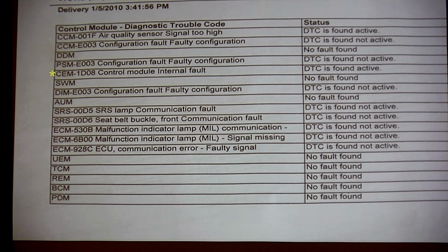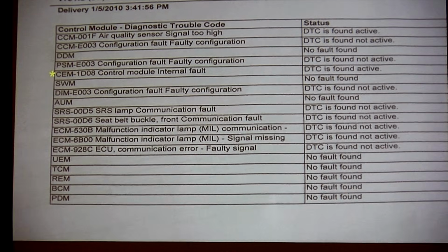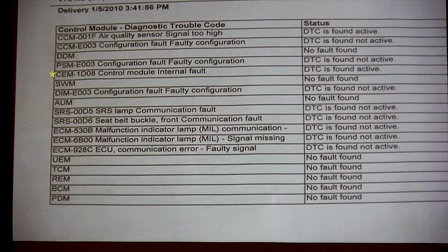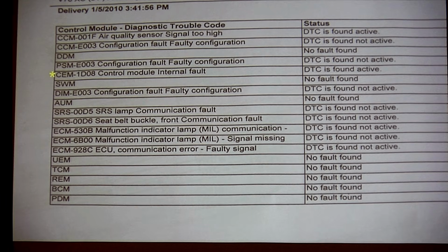Once you count to 256 failures and you hit that, that module is off of the bus. If it's the SIM, you lose the high side, you lose the low side, and your car doesn't start. Do you see why I'm interested in the SIM and I wanted to see the car when it first came up? Once you understand this stuff, it all makes sense. It's not that this car, oh, it died, oh my God, it died twice. No, the bus got kicked off. And once he's kicked off, he cannot communicate until you do a hard reset. That's the truth.